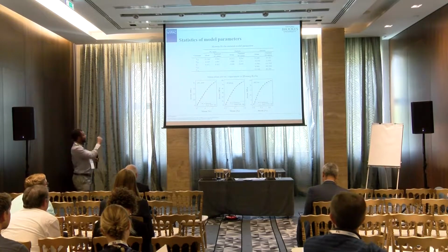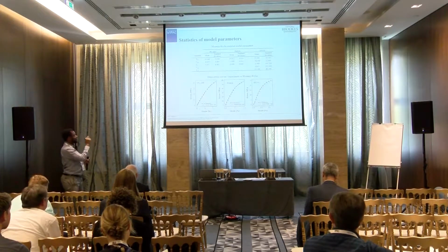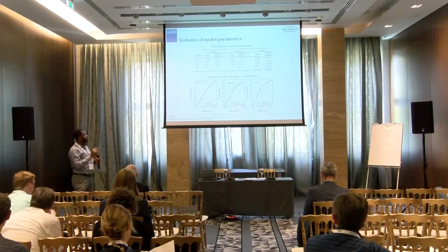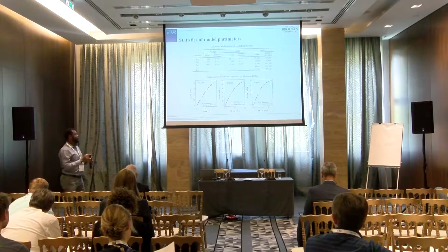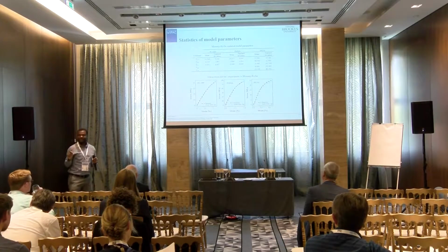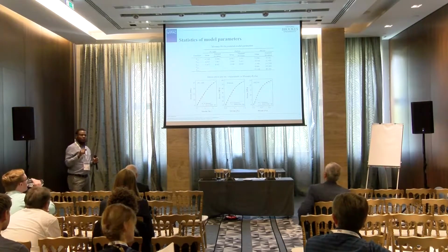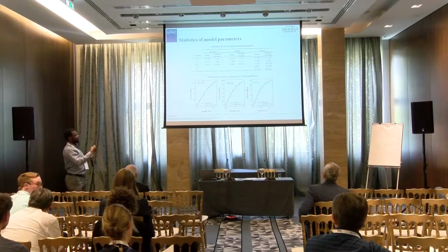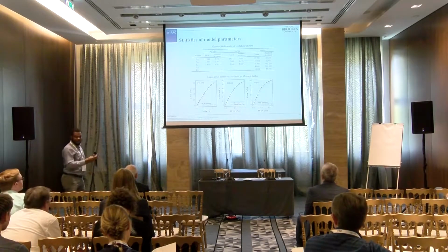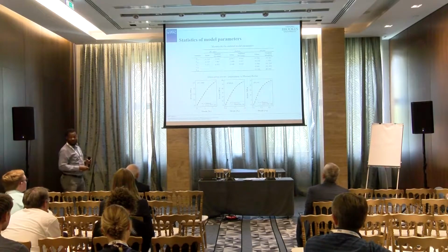And here we estimated the Mooney-Rivlin parameters I was mentioning earlier: C10, C01, C11, C20, and C02. Using the parameters, we constructed the stress, and then we compared it to the experimental stress. You can see the match there; they fitted very well.